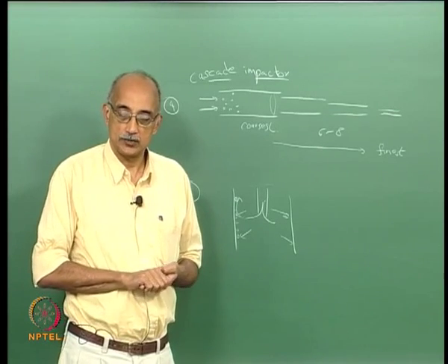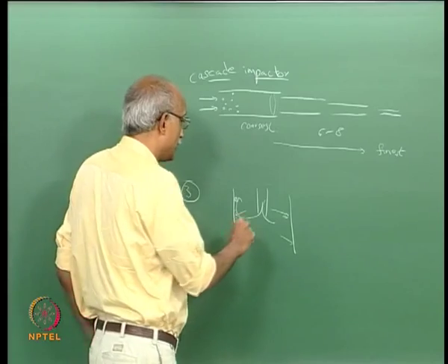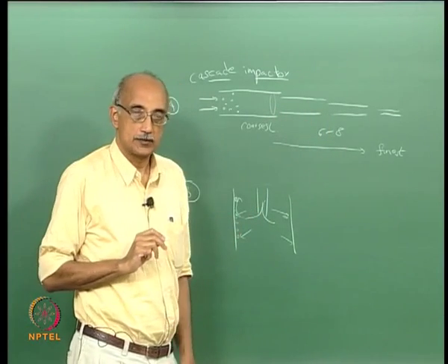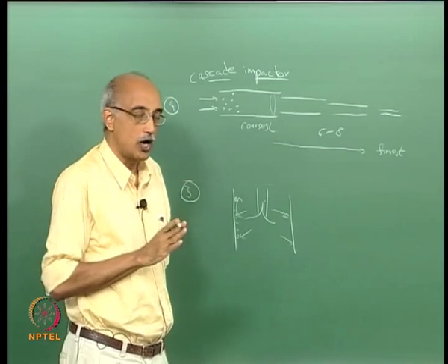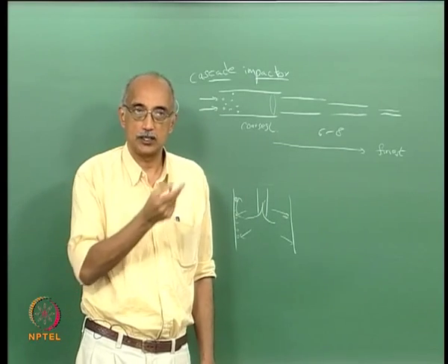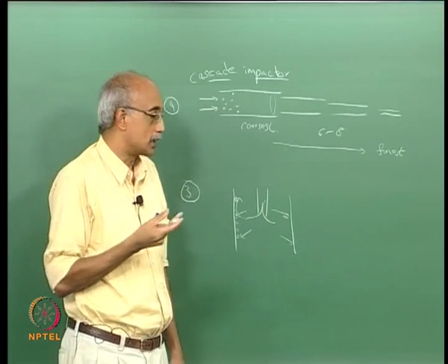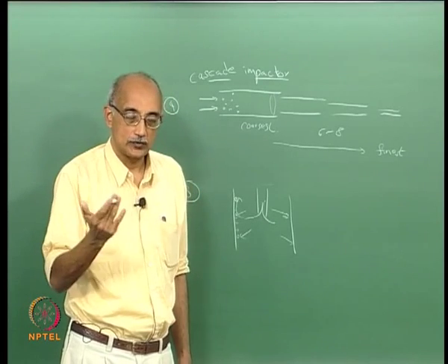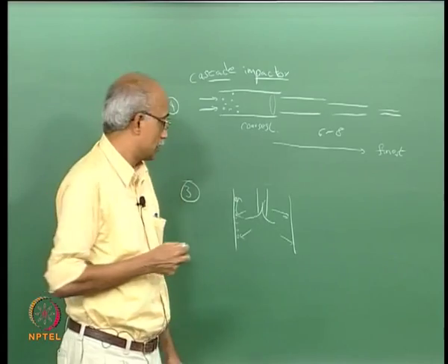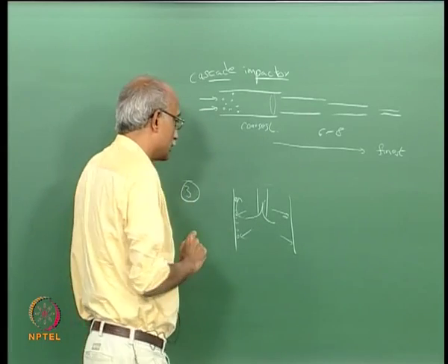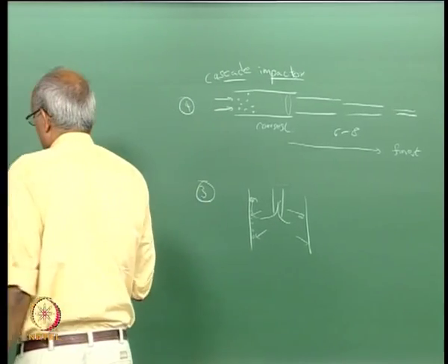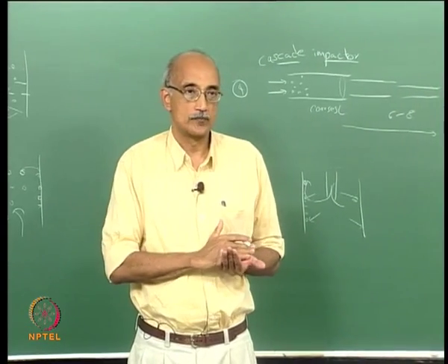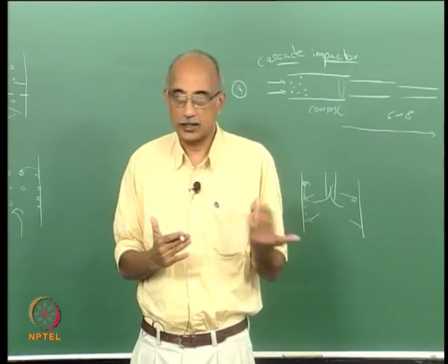Impaction, on the other hand, is very different. The particle actually deviates from the flow streamlines and normally impacts the surface, and it gets collected because of the high sticking coefficient that is associated with high Stokes numbers. So, the impingement collector is a way to collect particles in a slightly finer size range compared to what you can normally collect in a cascading impactor.